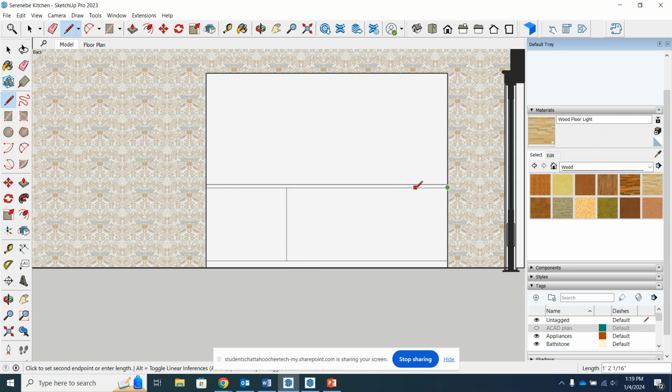If you want to type in feet, then you would type 3, single hash mark for feet, and hit enter. So just make sure you remember what measurements each system uses. It's now created a midpoint for each of these sections, so I can use that just to divide.